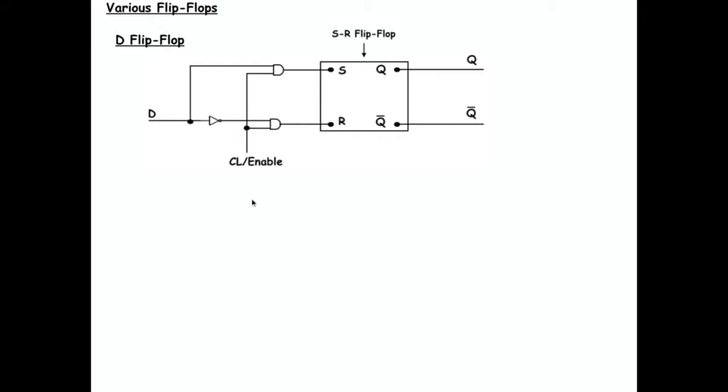In a second, we'll see how the clock signal is sort of like the passage of time. But whatever it is, it's going to be either 1 or 0. And when the clock is 1, whatever is going into this AND is just ANDed with 1, and it will be identity.